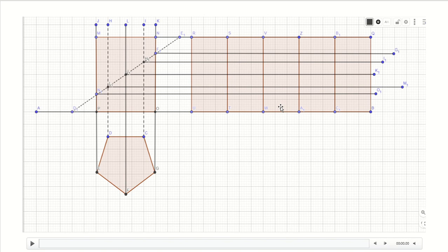Then, as you know, you are creating the development of the lateral surface. In the previous lecture I explained the creation of the development of the lateral surface, and this procedure I have explained earlier. After drawing the lateral surface development, you need to see where all the projected lines are meeting all the sides. Suppose if this is the side, that means after using the cutting plane you are getting a point here. Transfer that point over to here.